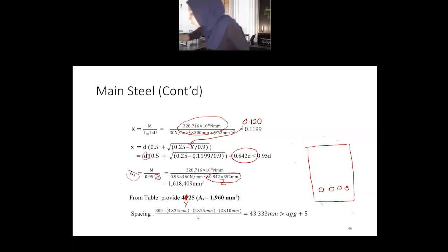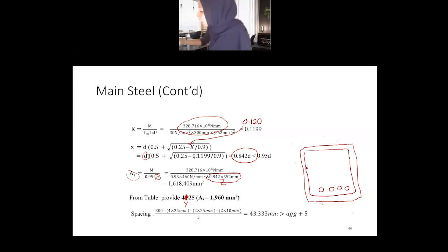Okay, tak cukup. Okay, tak kisahlah. Ini I lukis for the sake of nak bagi orang faham sahaja. Okay. Spacing kita nak check sebab kita nak make sure that in between this bar ada space for the concrete to be pour inside evenly and also for poker vibrator to vibrate the concrete below. Okay, kat bawah ni.